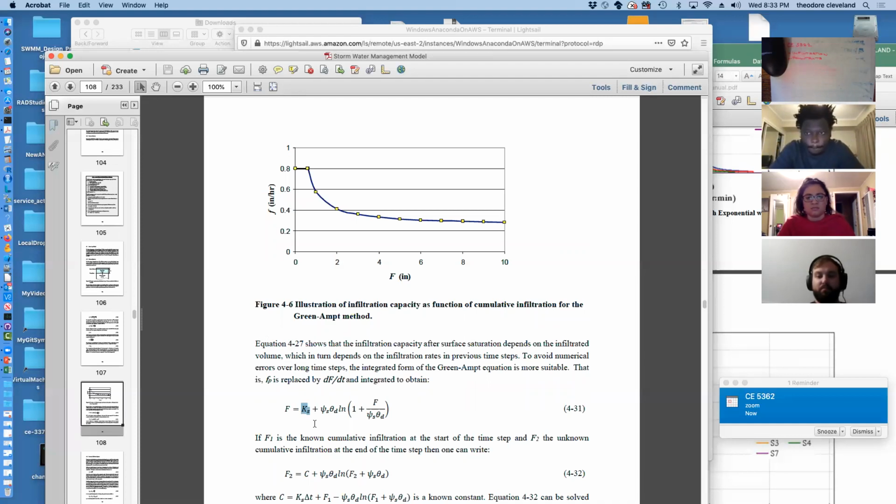And I'm being unnecessarily cynical there in certain contexts. That's money well spent. But any geotechnical laboratory can recover a saturated hydraulic conductivity for you. The moisture content at complete gravity drainage deficit can be computed using a, what's the device called? I've manufactured them. There's a hanging column permeameter. That's not the right name, but that's close enough. This value is also determinable in a laboratory experiment.